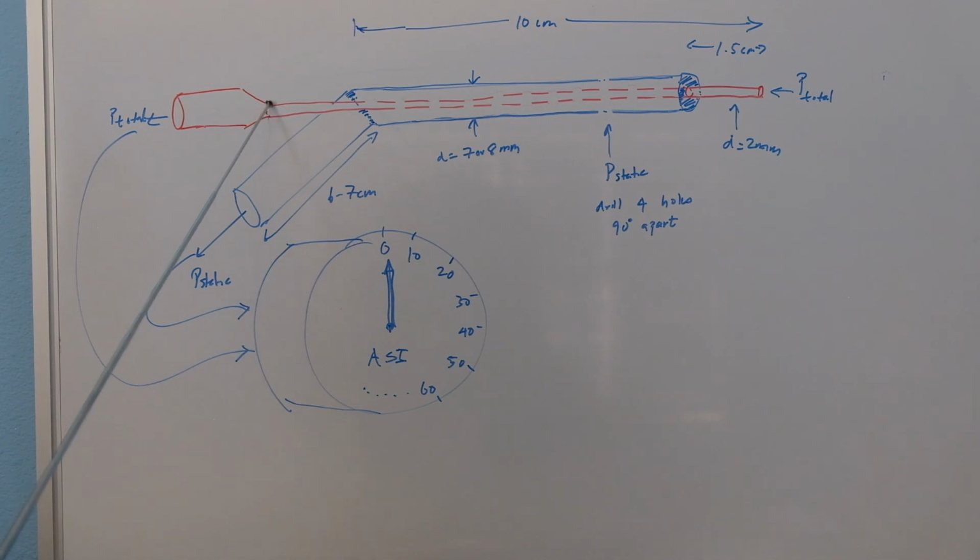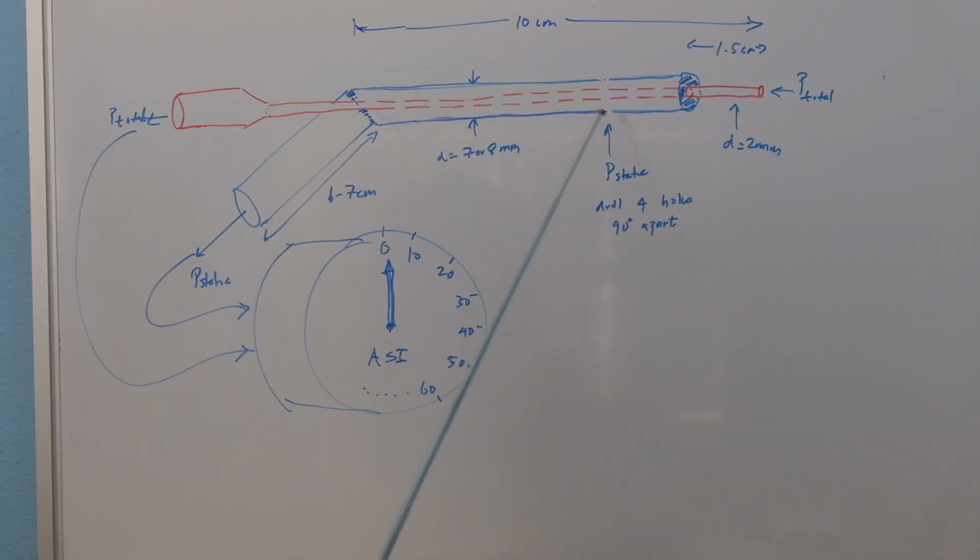And then on the other side, this small tube is then, I somehow crushed this bigger tube here and fitted it over here and soldered this, making sure that this is also a tight connection, because the main total pressure is all the way through this red tube here and goes to the ASI. So you shouldn't have any losses or any errors in this one. The static pressure is somewhat easier to handle. It is picking up just a still air pressure around this instrument, which has no dynamic pressure in it. So then these two tubes are then with the polyethylene tube.